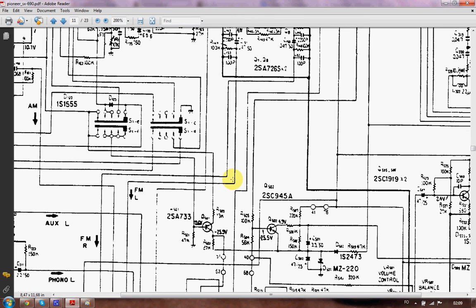And if there's a missing, let's say, a missing left channel only when we choose our phonograph, but all the channels work fine with all the other applications, well, it could be a broken wire going from the phono input interface to your phonograph signal processor, aka preamplifier.